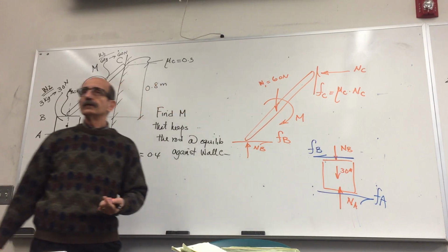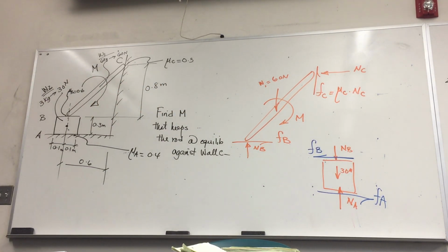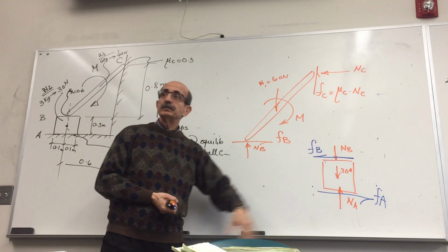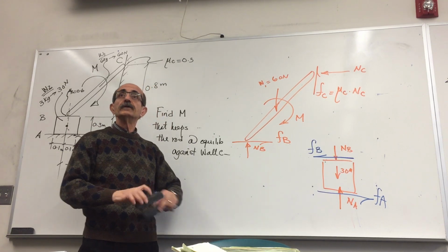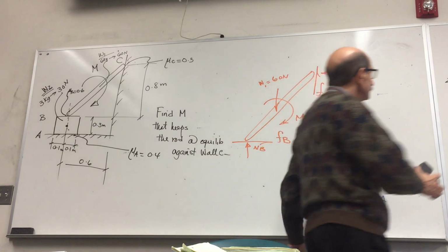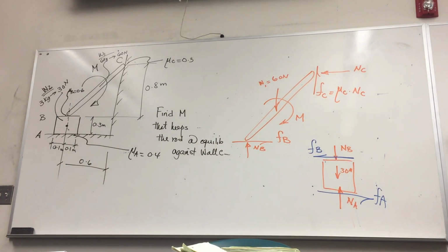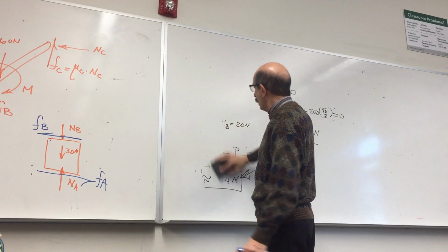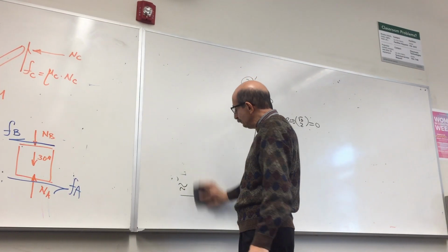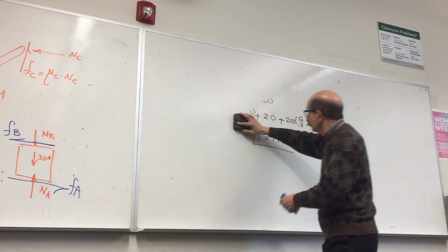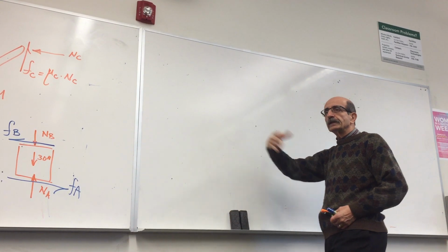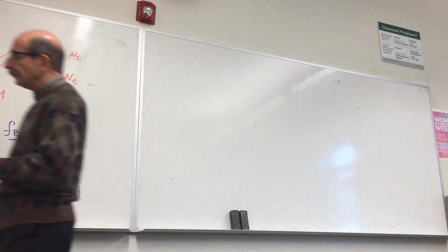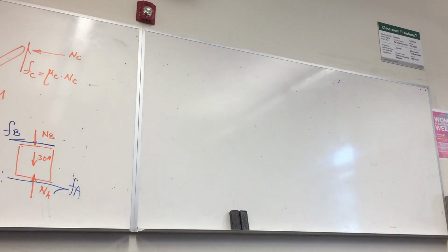So as you can see in this problem, in order to draw the free body diagram of the second piece or part of the problem, you really need to think very carefully how the motion may occur. And that's really the key. In contrast to frame problems, you could make any assumption as far as those forces of contact or connection, and then your solution leads to a negative number, so you change the sign. In friction problems, you have to establish the correct direction.